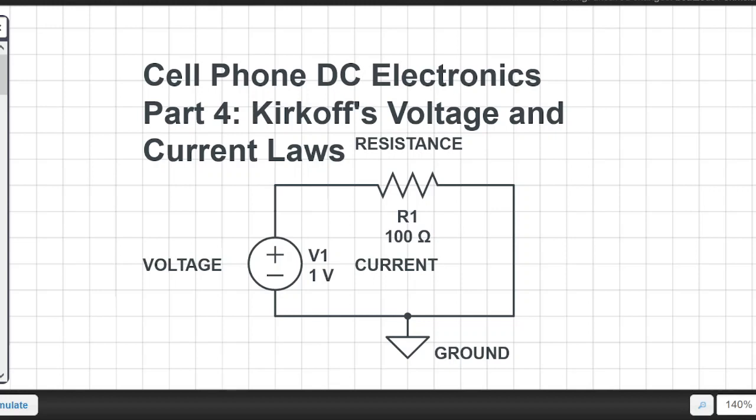Each component, even though current is harder to measure from outside the circuit, should have a voltage drop. And if it doesn't, then essentially that component could be something like failed, shorted to ground, opened, something along those lines. You shouldn't reach a 0 point until the very end when you reach your negative pole, or your ground pole.